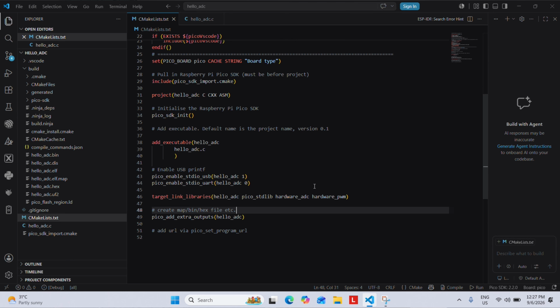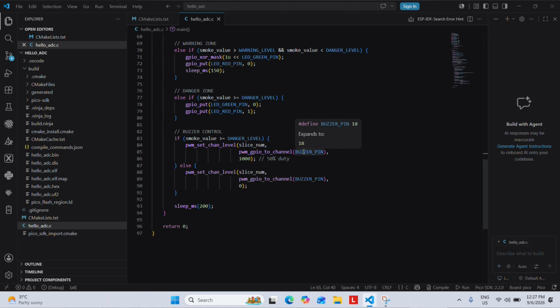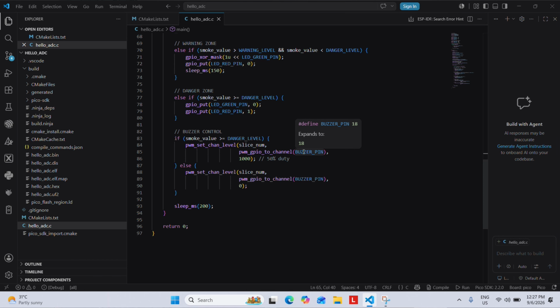From this source code itself, I wouldn't say I followed the datasheet fully. I just tried to play around with the ADC reading and see what the reading is in a practical approach. For example, I turn on my LPG and see whether there is gas presence, what value is involved, and from there I just manipulated the ADC reading based on the practical application. So I have a lighter here. For example, when I flame it up, it will turn on the buzzer.